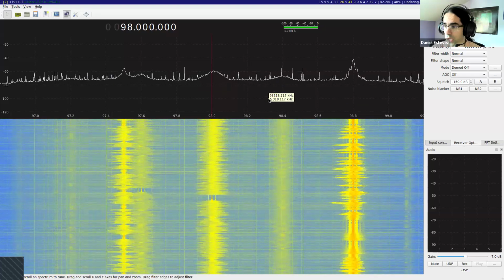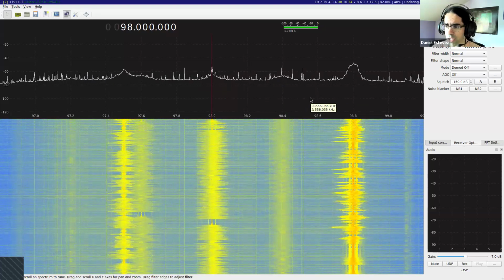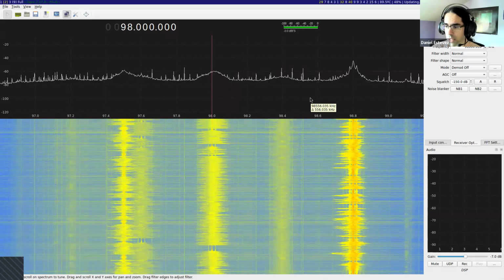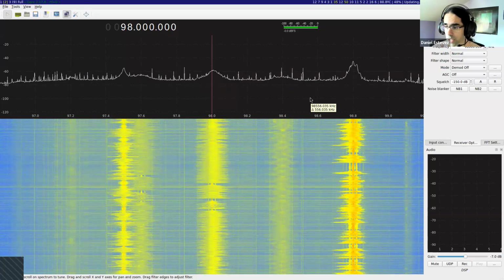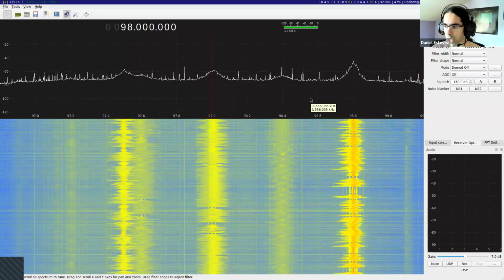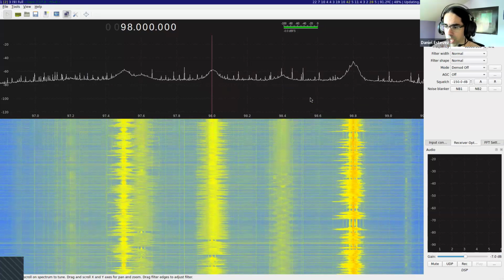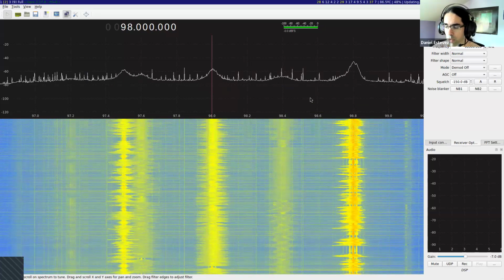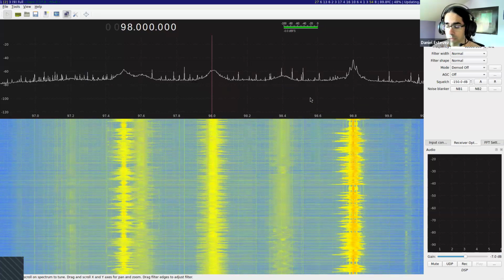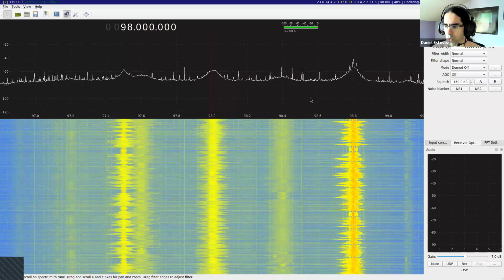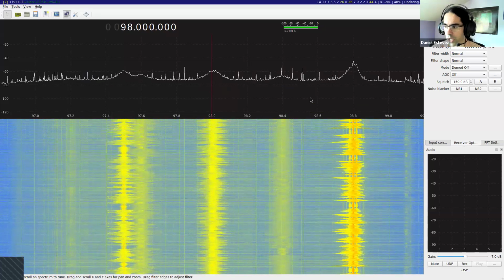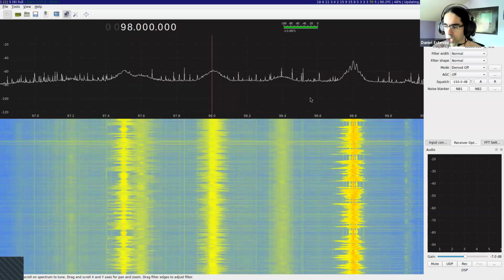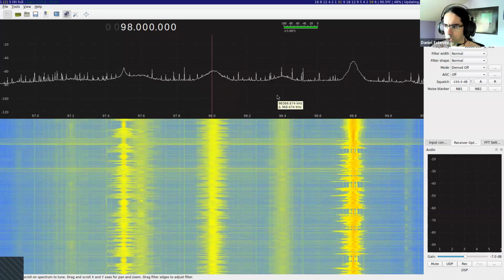We have a bunch of FM radio stations, and we are receiving all of them at once. That's one of the interesting things about a software-defined radio: we can capture a chunk of spectrum and then process all the signals in there, as opposed to, say, a regular FM receiver, such as the one you might have in your car, which can only tune to a single FM radio station. And it needs to be in the FM band, and it can only do that.